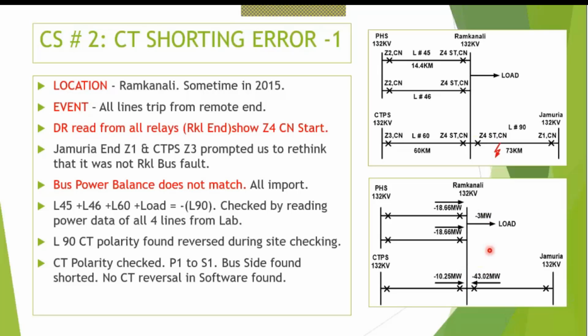What was found was that all the powers were export powers. Now one thing we know by virtue of our experience is that this particular bus is always providing power to this particular bus, because there's a generator connected over here. So always the power flow is from this PHS, Panchet Hydel we call it, to the Ramkanali bus.